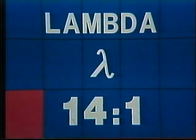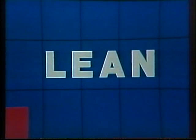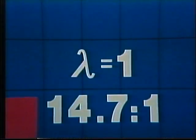Time for a brief review of lambda. The lambda symbol describes the air-fuel mixture, ordinarily about 14 parts of air to 1 part of fuel. The engine runs rich, lambda less than 1, when the mixture has more fuel than can be burned with the air. The engine runs lean, lambda more than 1, when the mixture has more air, when air is left over after all the fuel is burned. Operating right at lambda 1 is important for emission control. So lambda 1, 14.7 to 1, is normal for warm engine, part throttle operation.